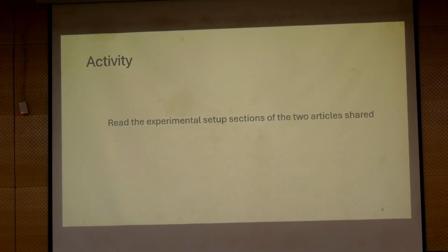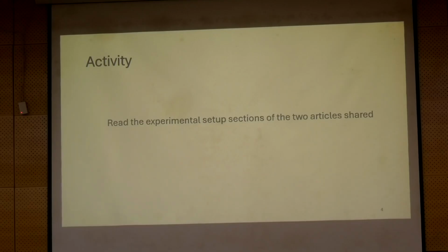More or less, there are only two approaches that I have seen in literature to introduce air gap eccentricity faults. The one that I am going to present is what I have in my lab currently, and this is reasonably easy to make compared to some of the setups that I shared with the article. The compromise is, with this setup, you can only achieve certain fixed or discrete values of eccentric severities. Okay, you cannot achieve continuous variation of eccentric severity.